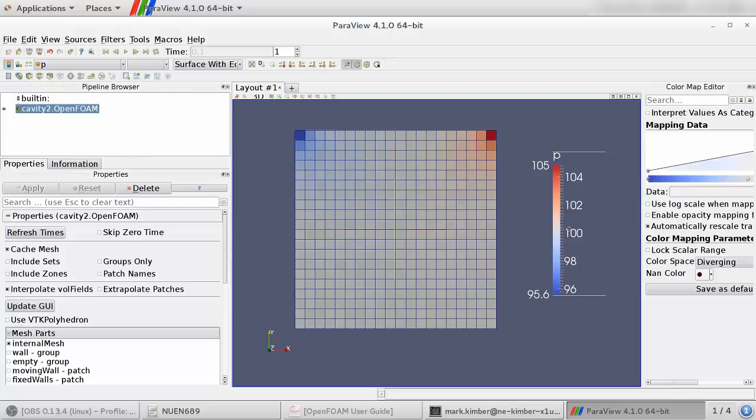So if you recall from one of the homework problems where we looked at the square annulus, we had all Neumann boundary conditions. In other words, from a thermal standpoint, we had insulated boundary conditions on the outside edges, and then flux coming into the channel from the inside square. Because those are all Neumann boundary conditions, we have to specify a temperature somewhere. And what you should have found is that whatever you started with in your initial conditions tended to be the nominal temperature on the inside of the flow.